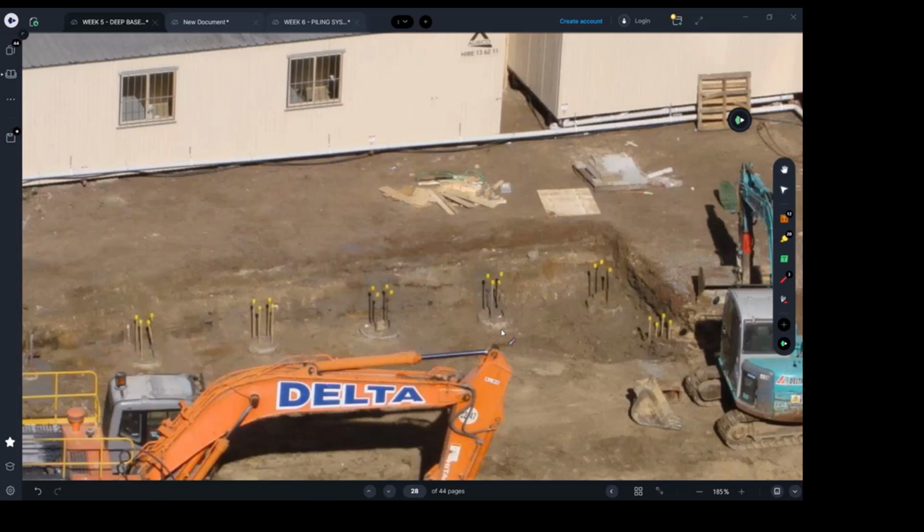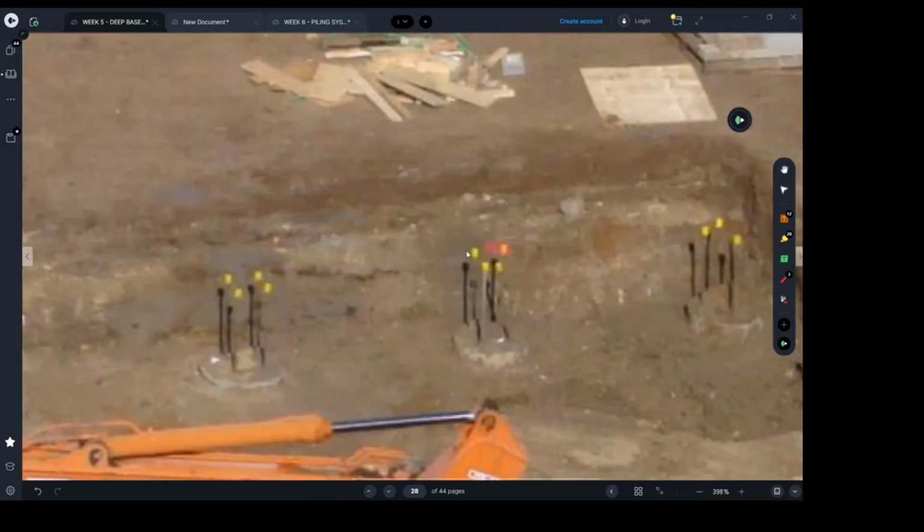That's in a self-supported soil, and also when you have short piles, like within 4 to 5 meters, and if the soil is stable. If not, we use the CFA method, where we dig the hole, and as it gets to the bottom of the pile, it will start pouring the concrete, and then you submerge the cage and make sure the cage or the steel is sticking out to get it connected with the pile cap.